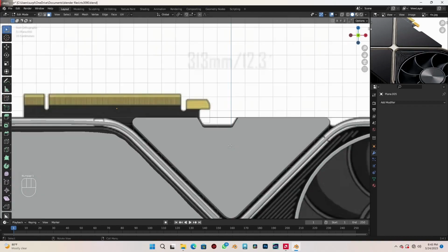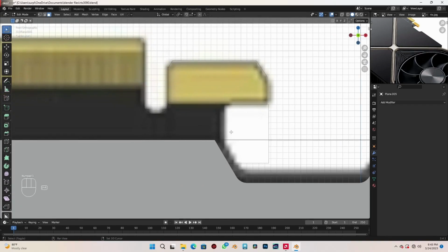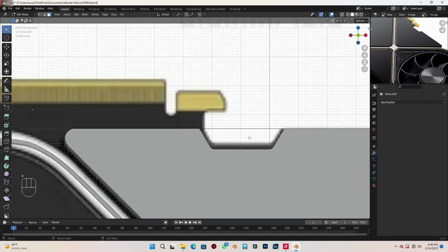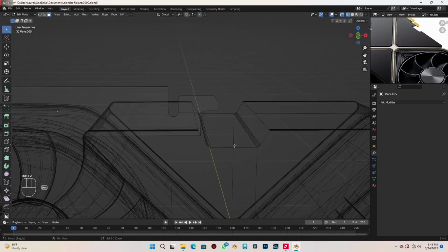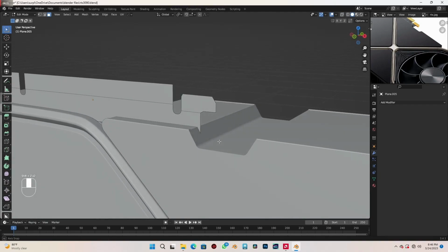Okay, I think we also need to take this part out too. So activate your knife tool again, and let's drag this here, and over here. Enter to confirm that. Select this face and this face, X, delete face.